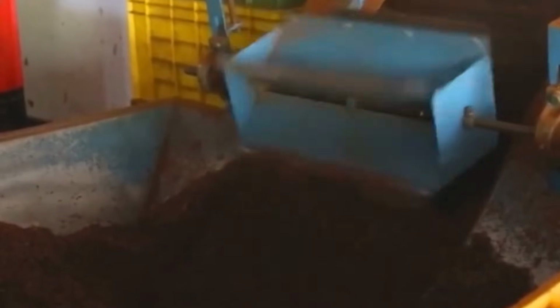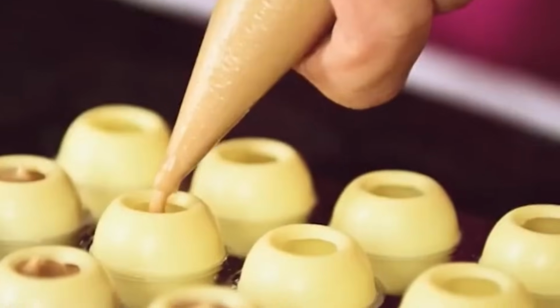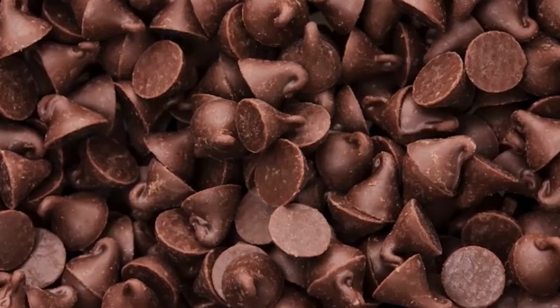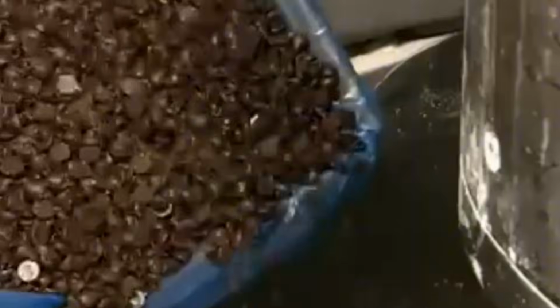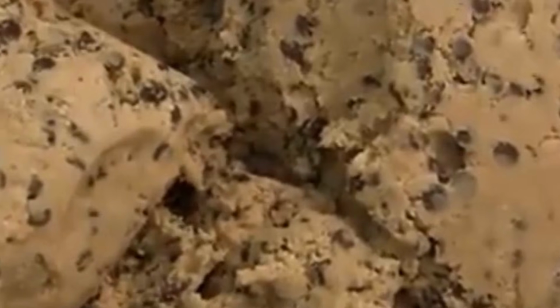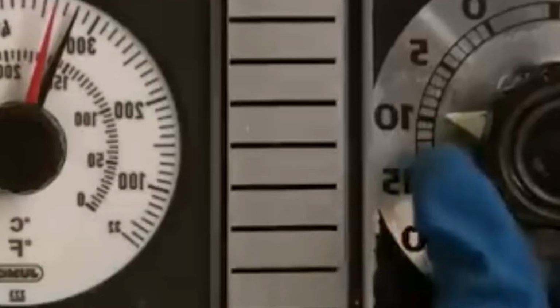Portioned dough enters an extrusion-based depositor system. The depositor uses servo-controlled pistons to extrude dough through circular nozzles onto a moving oven band. Each cookie unit is dropped at exact intervals to maintain spacing and size. Depositor nozzles are non-stick coated and fitted with sensors to detect flow irregularities.